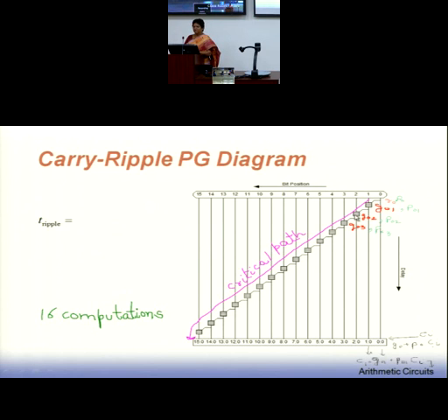Similarly, the moment G02 is available to me, I mix it immediately with Ci, which is known to me, and the sum and carry at this position can be immediately computed. But you can see every time you compute a new block generate function, it is always one step delay included in that, which is exactly similar to something which I understand in terms of carry.